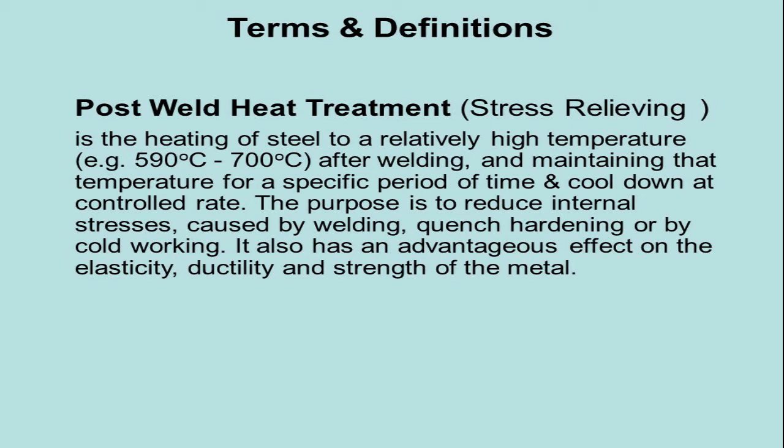Example: 590 degrees centigrade to 700 degrees centigrade after welding, and maintaining that temperature for a specific period of time and cool down at a controlled rate. The purpose is to reduce internal stresses caused by welding, quench hardening, or cold working. It also has an advantageous effect on the elasticity, ductility, and strength of the metal.